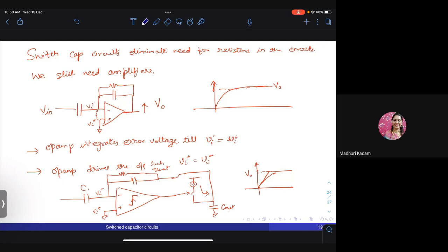So it turns out that when you implement a circuit with comparators and switches like this, the overall power of the circuit will be much smaller than what you have for the op amps. And that makes sense also, right? Because when you try to make an op amp with high linear range, you will end up burning a lot of power to increase the linearity range. But if you are using comparators where linearity doesn't matter, you can do it with much lower power.